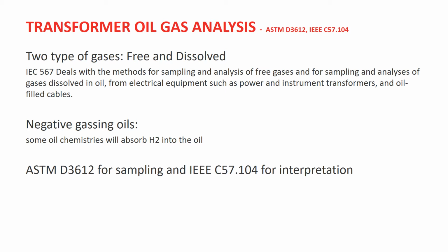There are transformer oils in the market with negative gassing property which will absorb H2, or hydrogen gas, into the oil. Using this type of chemistry, we reduce the maintenance operation and cost of the transformers.